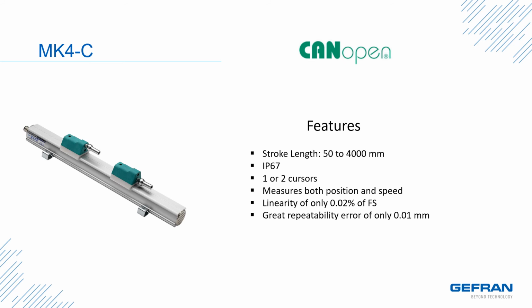It has a stroke length of between 50 and 4,000 millimeters. It is rated IP67. It has either one or two cursors. It measures both position and speed, has a linearity of only 0.02% of full scale, and great repeatability error of only 0.01 millimeters.